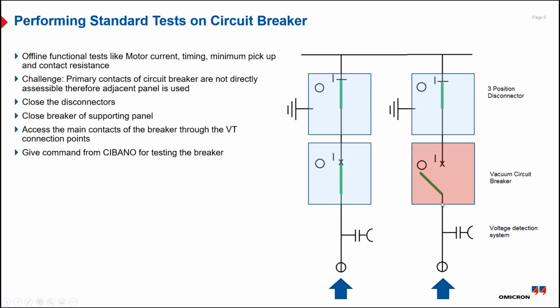This way we can send signals like current and measure the voltage to do timing measurements, to do contact resistance measurement, and we can also do motor current, minimum pickup, all the common tests which you would do for healthiness. You can do it in this method.